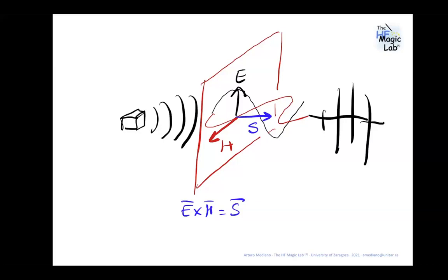It's not mandatory. It depends on the layout you have, the size of the package of your components, and if at the end you cannot minimize the nanohenries and the picofarads of the resonances, you will need some kind of snubber to avoid the peaks. So I recommend to minimize the possibility of ringing with a good layout and components placement. And if this is not possible, then you will need the RC snubber.